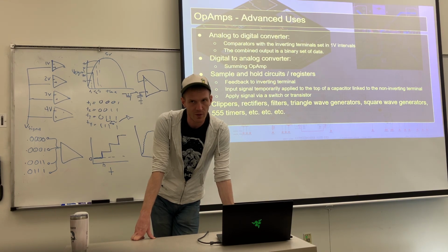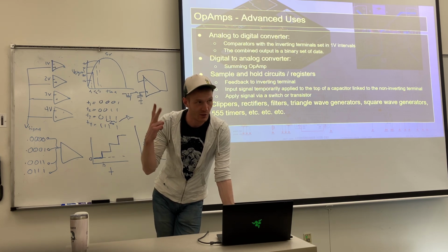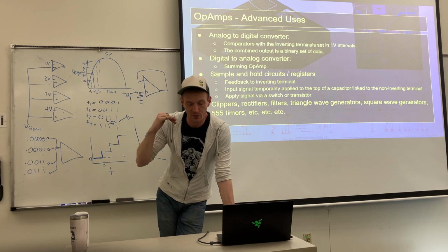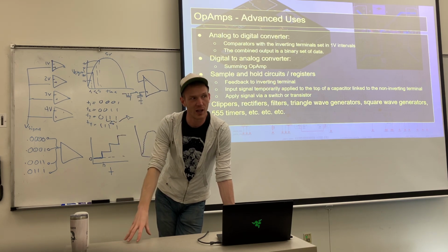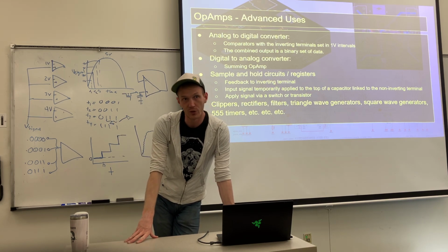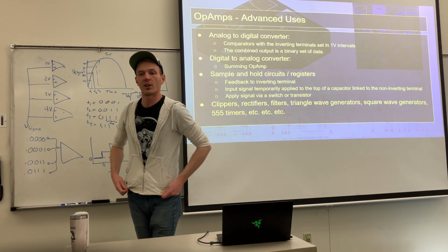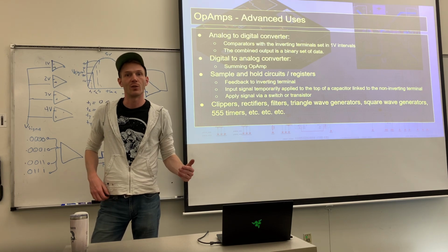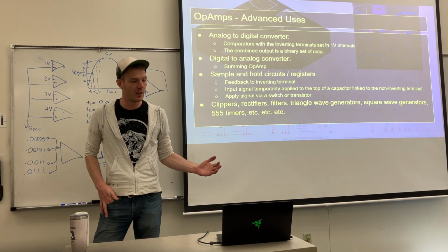So, things to remember about OpAmps. Part of their purpose is in the name. They amplify. You can use them to do very direct comparisons to say, is this higher, is this not higher? You can do voltage followers to just follow the output, whatever you're doing. You can do math with them: integration, differentiation. You can sum, you can subtract, stuff like that.